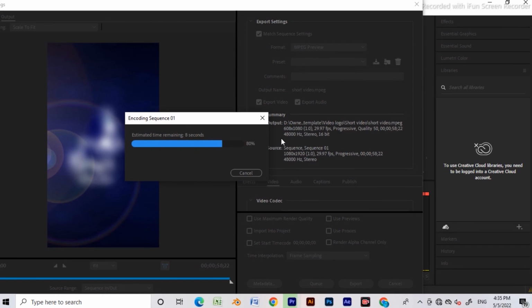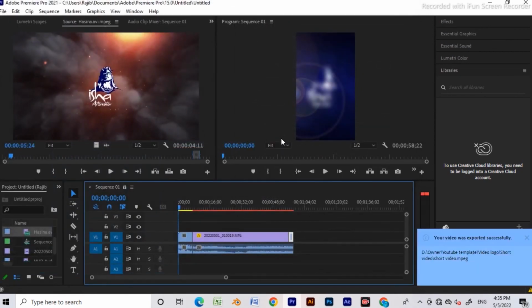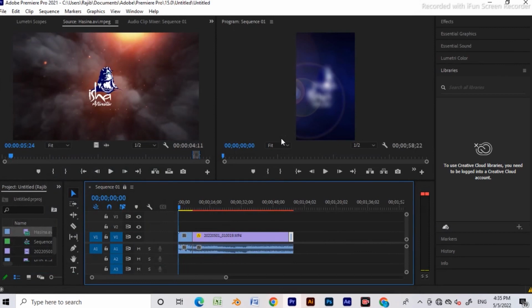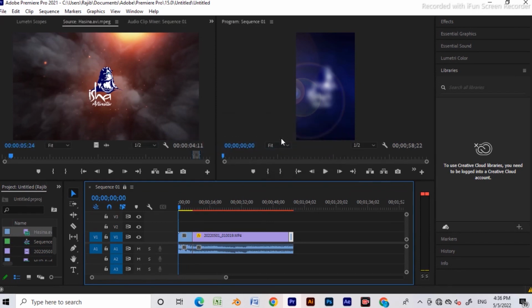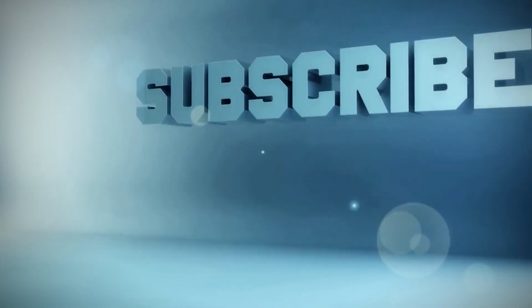But there is a problem. It is showing these random numbers after the dot. But we can fix it very quickly. Simply, click on the expression box, and here add Math, with capital M. Dot round. Then open bracket. Now go to the end position, and close the bracket. Make sure to enter the script as I have typed. Else it won't work. And the problem has been fixed now.